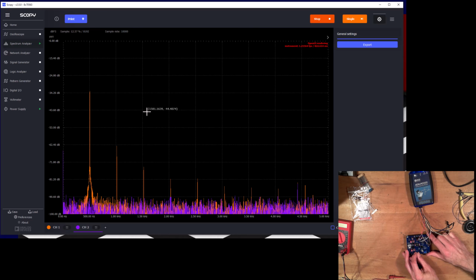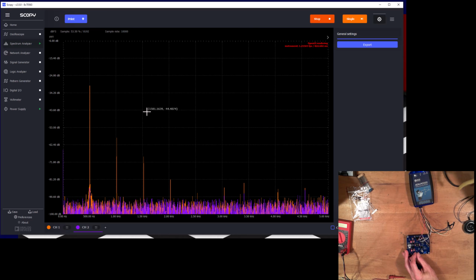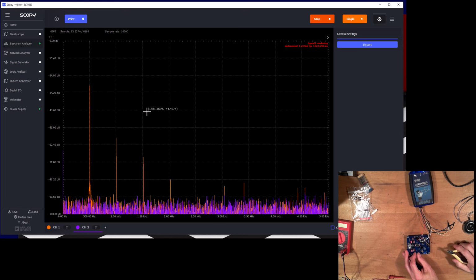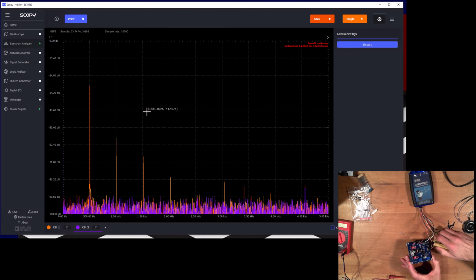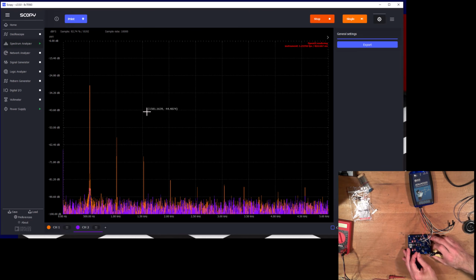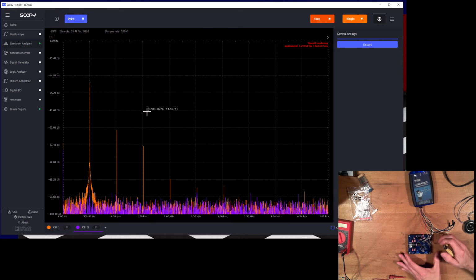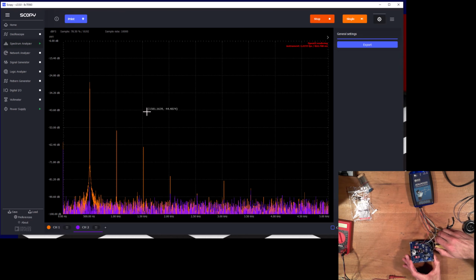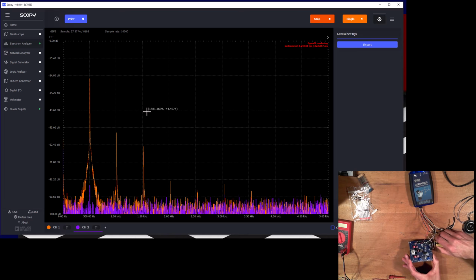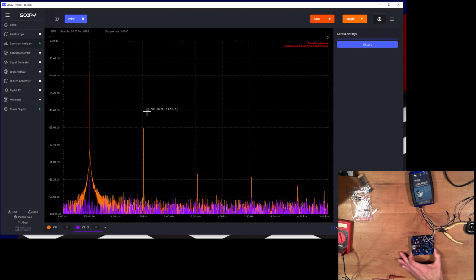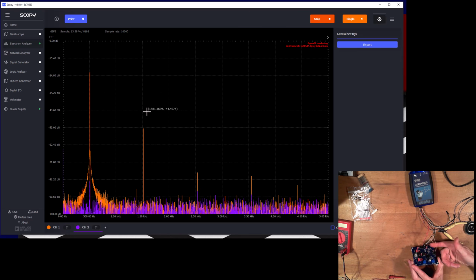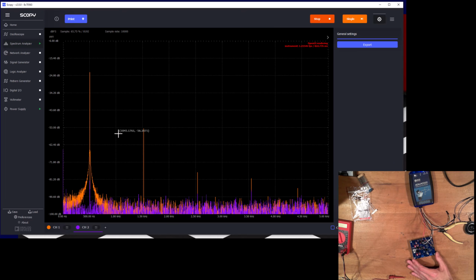Okay, so I wanted to do this. I have not practiced this, so let's see what happens when I clip out that Schottky diode. Okay, so let's make sure our gain is high enough to sustain oscillation. Let's clip out that Schottky diode. Wow, look at that. I've clipped the wire and the second harmonic just disappeared here.